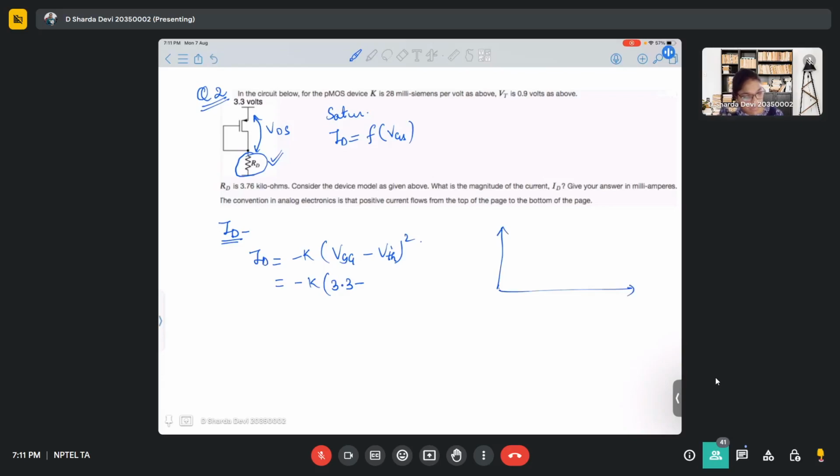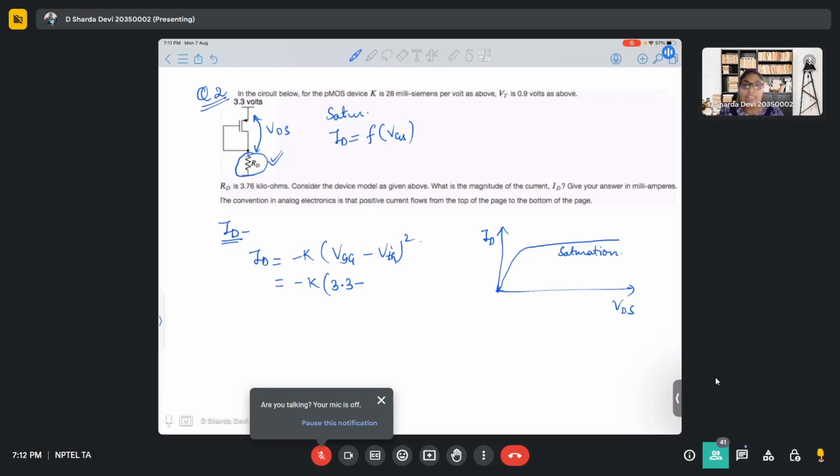See, when I say a MOSFET is considered to be an ideal MOSFET, that means I want this characteristic, which is like ID completely parallel to VDS. Now, if I'm saying that ID is not changing with VDS, because this is the saturation region, right? Is there any relation between ID and VDS, considering that VDS has no impact on ID?